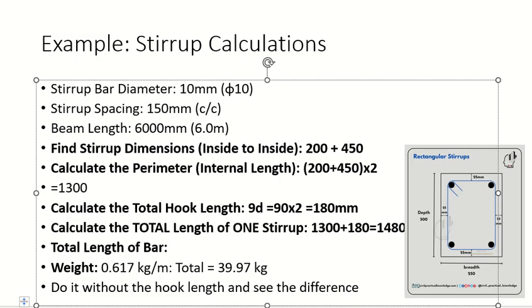Now these stirrups are at how much spacing? 150 millimeter center to center, right? And how much length do I have? 6000. How do I calculate the number of stirrups now? Divide what by what? 6000 by 150. The total length divided by the spacing, right? Are we done? Is this a number? No? Very good. Tell me, what are we missing? The diameter of the stirrup.